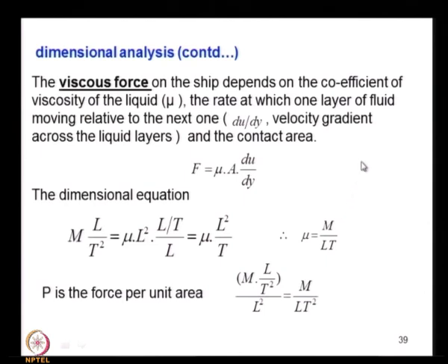So, when you come to viscous force, you just find out what is the unit of mu, what is the unit of dynamic viscosity. We know the relation from the Newtonian relation, tau is equal to mu into dou u by dou y, or du by dy, that is the relation given for Newtonian. So, that into area gives the viscous force. Tau is a shear stress.